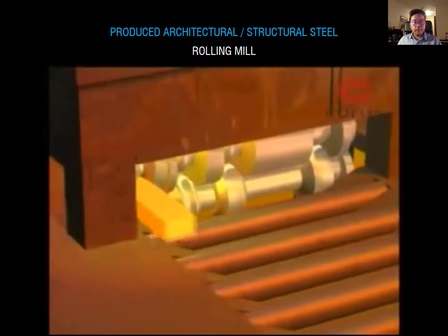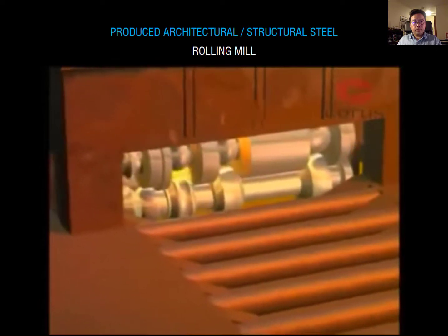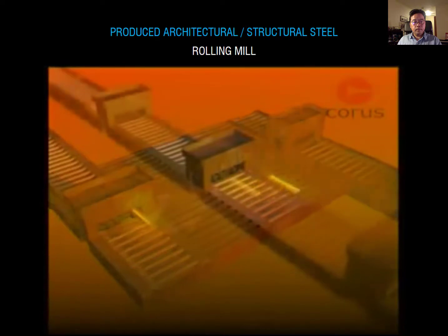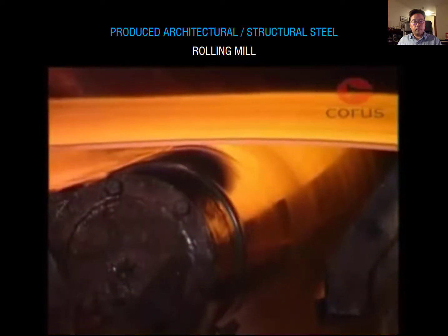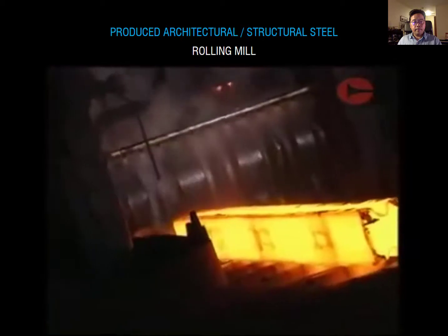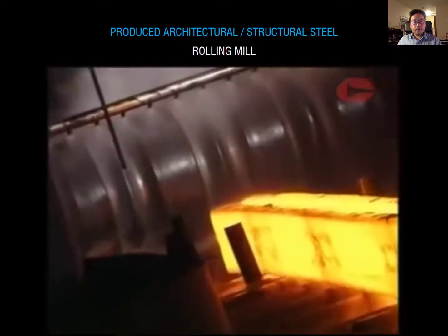The layout of a rolling mill can vary from a simple single stand mill to several stands positioned either side by side or in a line. The mill rolls themselves can either be plain for flat products such as strip, used for products such as cladding, or profile for sections, beams and columns for use in construction.